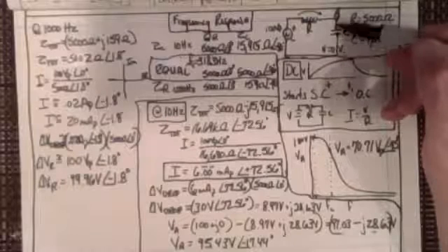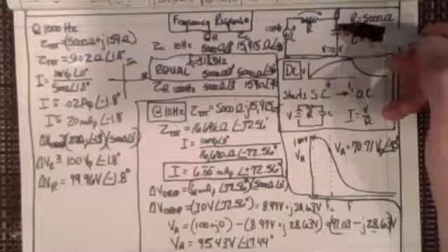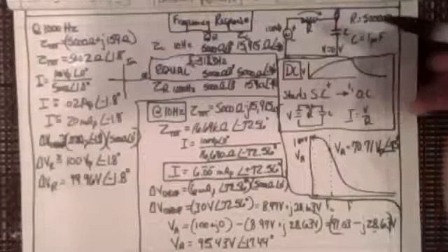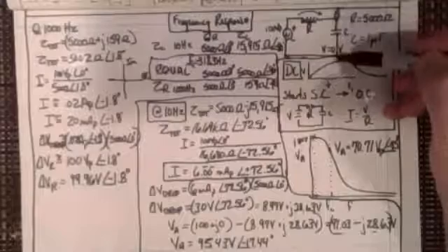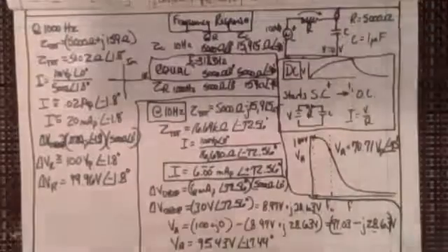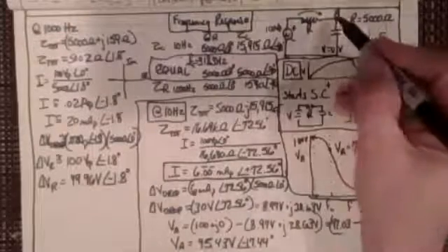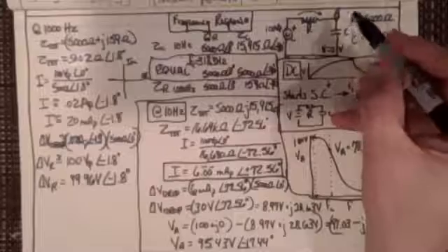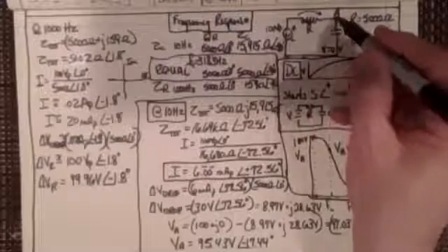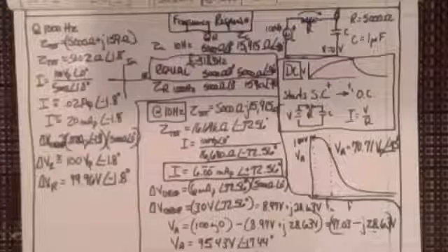This is holding off more voltage all the time, at low frequency. At high frequencies, the voltage is just flowing right through the capacitor, and this is going to 0, and that's why you get the 100 volts across it. All right. Okay.